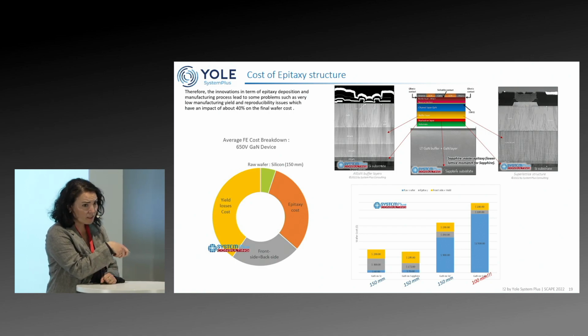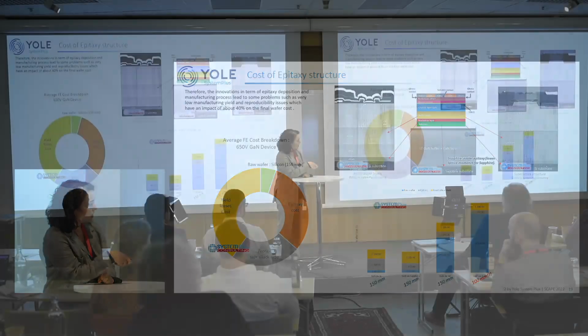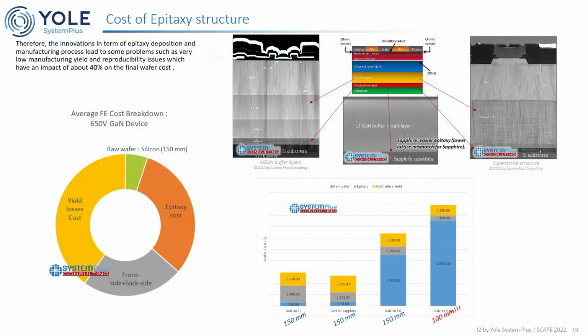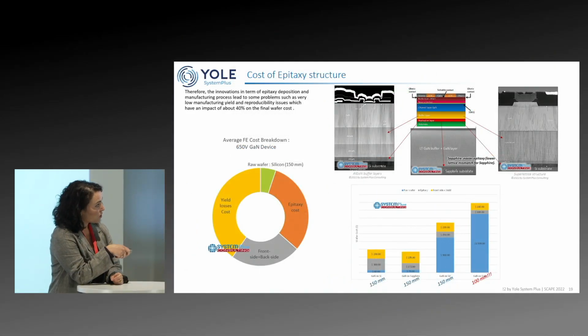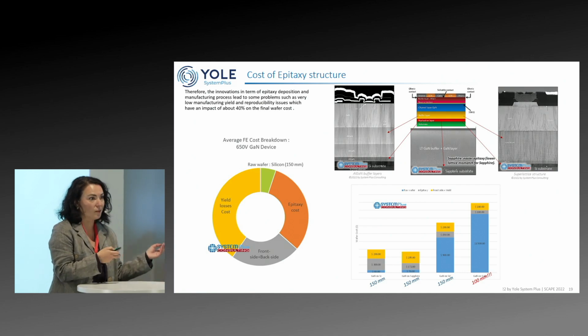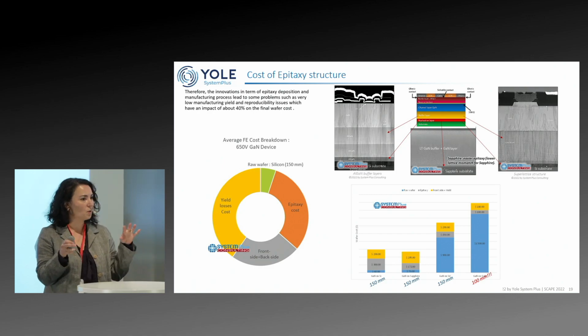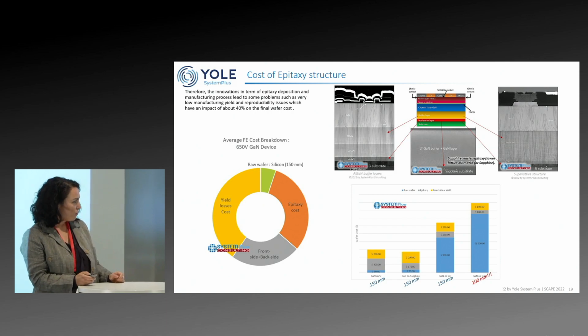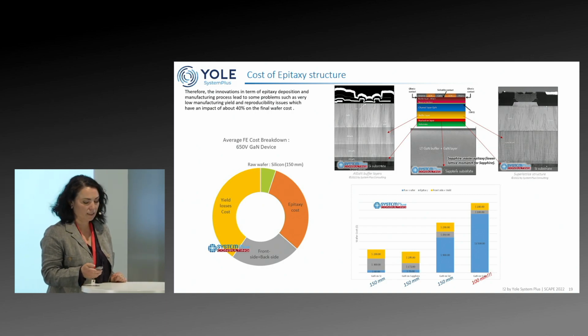It's quite interesting, because the substrate is a bit more expensive than silicon, but since the mismatch is much closer to gallium nitride, you can work with a thinner epitaxy. Then you have gallium nitride on SiC, where we go back to the problem of the cost of the silicon carbide substrate, and then you have GaN, so a completely vertical integration of the device if you use a GaN substrate.